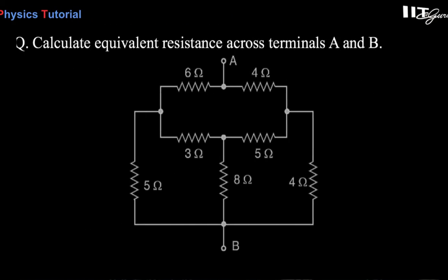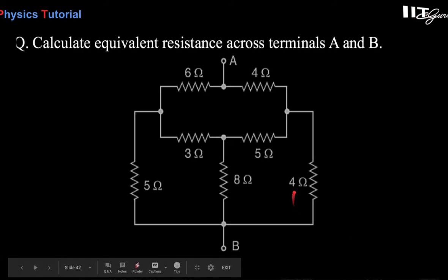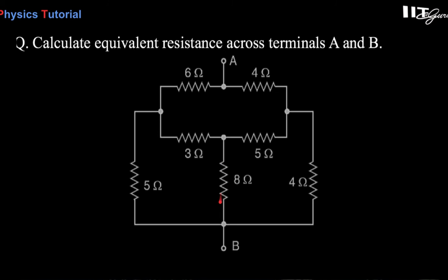And let's see one more question. In this question, it seems like a Wheatstone bridge, but once again, due to this point, when the wire is connected, that is the 8 ohm, this disturbs it. When this disturbance occurs, once again you have to rush to the loop law, but the loop law is too cumbersome and it is not easy to handle in a short span of time. So within this short span of time, better just go for the star delta rule and go ahead.